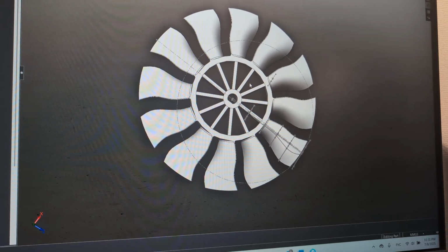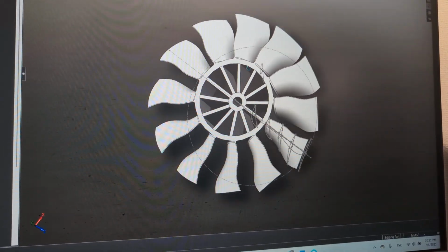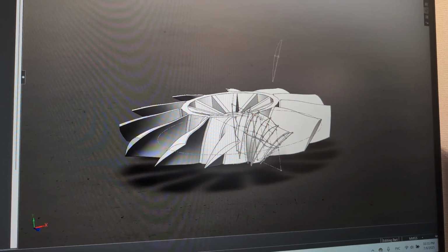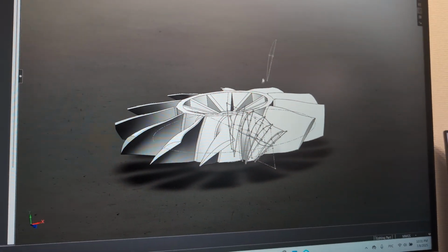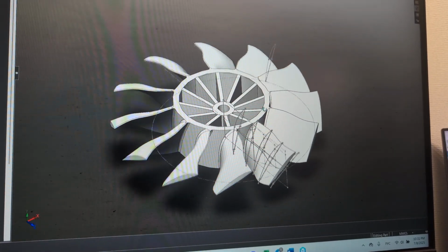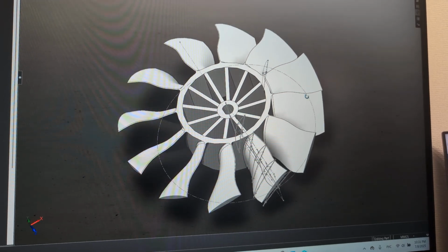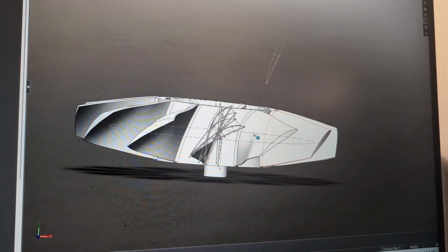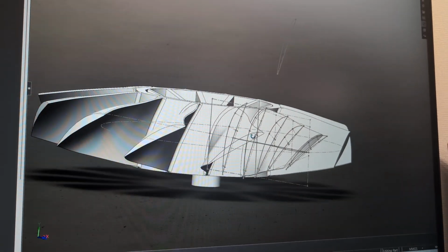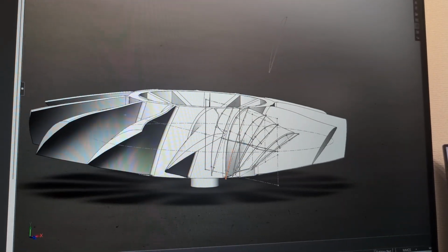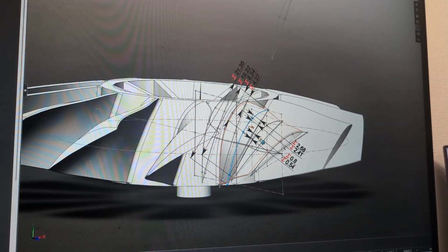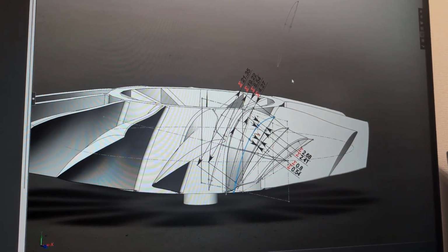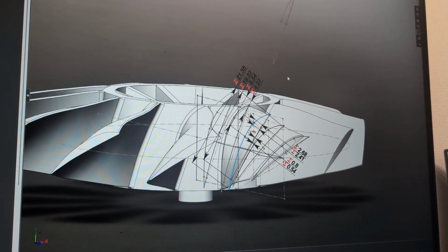Okay, so you usually start from defining the pitch angle, how fast your propeller is going to spin, and how fast the air outtake you need to get. Based on that, you're going to get your efficiency and all the pitch numbers. The pitch is usually defined in inches per rotation.